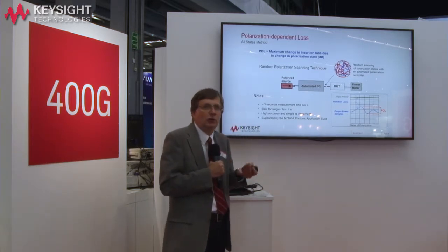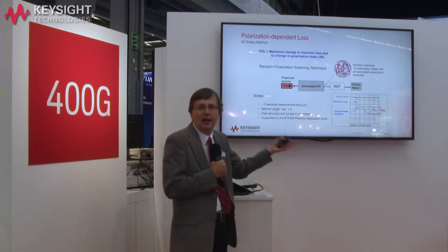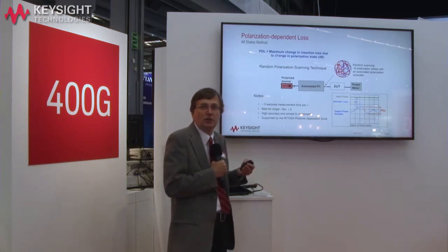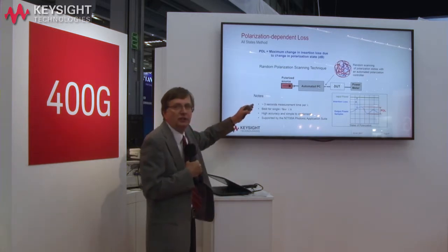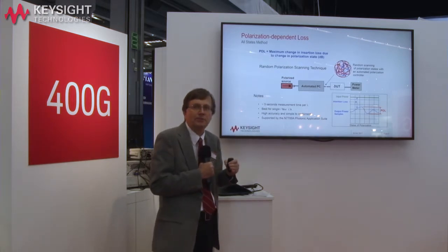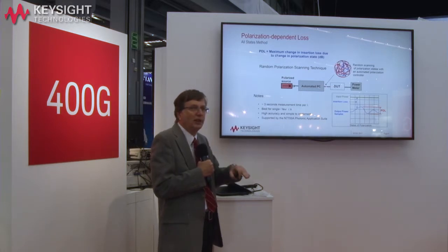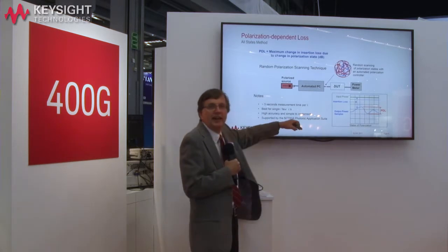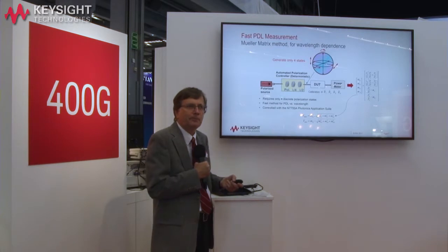That's fine if we only need a measurement at one or a few wavelengths, but very slow if we have to do that thousands of times, like we would if we wanted, say, 10 picometer resolution across a spectral range. And so we use a different approach. Where this is, however, very useful is when we want to measure something with very high polarization extinction, because then you really need to make some measurements very close to the minimum of the signal. And we do have a way to support that in our software in addition to this method,